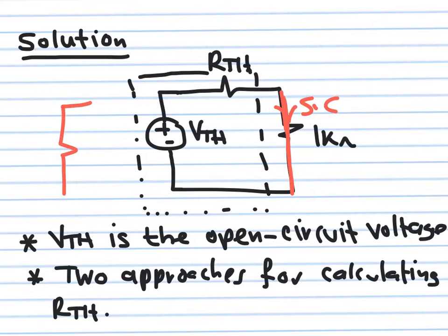Okay, so if you have R Thevenin here, what I do, if you can find the input resistance looking between these two terminals, the same terminals we used before, after you get rid of all the independent sources, with short circuit now, or it's not there, then the input resistance is R Thevenin. But if you have dependent sources,